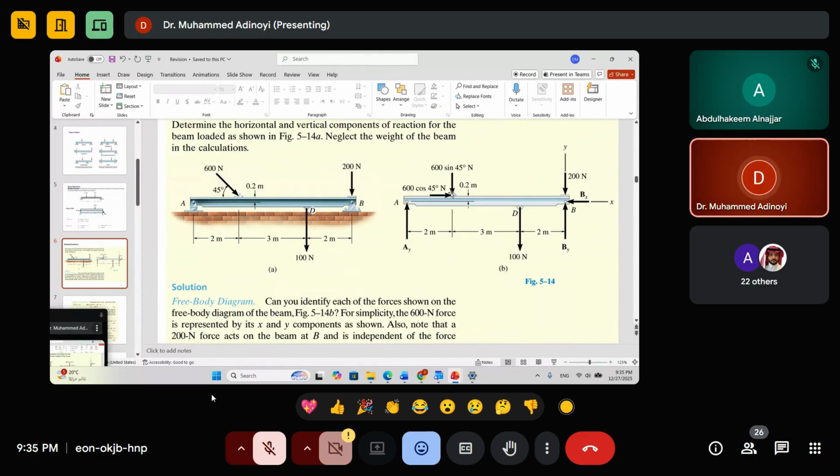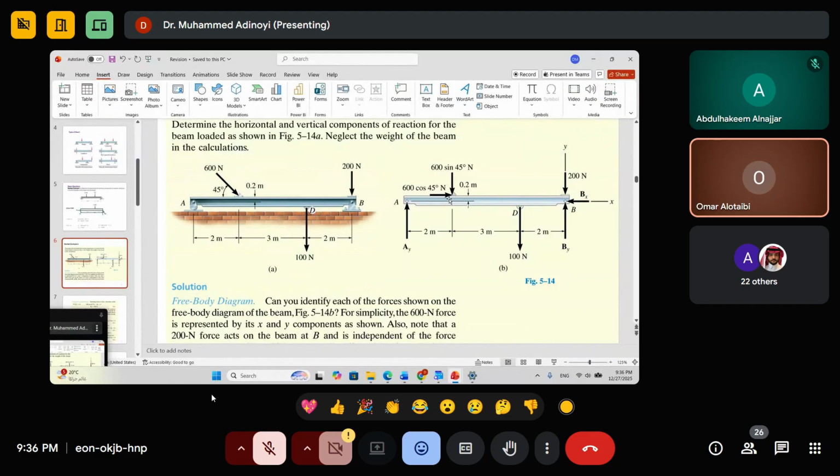It depends, because the direction of this arrow can also change. If the direction of this arrow changes, it becomes clockwise, and the moment goes the opposite way. So if it's above the x-axis, it will be negative, always? It depends where you are taking the moment. If you take it at B, it is clockwise because it is above the x-axis. But if this arrow changes and it is still above B, it is now going to be anti-clockwise.